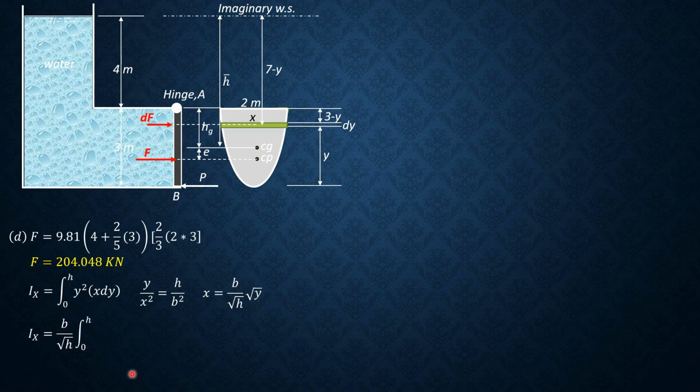Let's derive first the moment of inertia of the parabola, although it was 18 over 175 bh cubed, the formula. Let's show it now. So y squared, times b over square root of h, then square root of y dy. Let's copy: this is y to the 5 halves. The integral is b over square root of h, then y to the 7 halves over 7 halves from 0 to h. So simplifying this integral, Ix is 2 over 7 bh cubed.